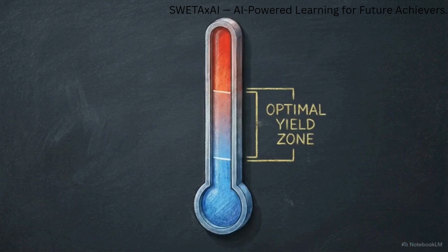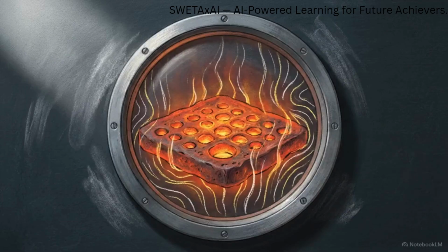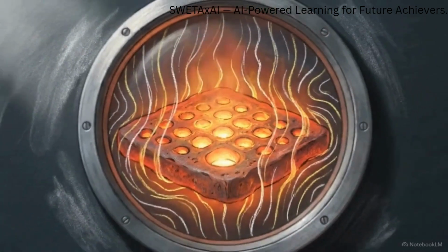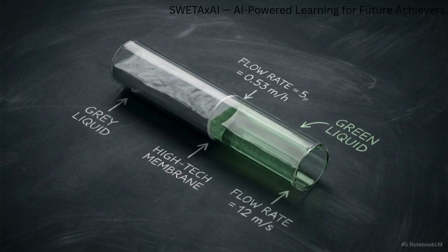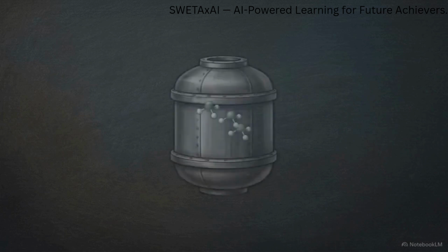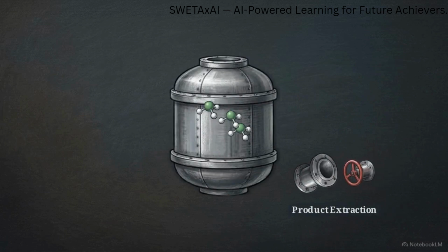The third and most crucial manipulation is a shift in concentration. A truly closed system is inherently flawed. If ammonia accumulates inside the tank, the reverse reaction will inevitably speed up and stall the entire process. Engineers solve this by building a continuous extraction mechanism. A condensation pipe actively siphons away liquid ammonia as soon as it forms. The closed system becomes an open loop. It extracts product from one end while simultaneously injecting fresh nitrogen and hydrogen into the other. This prevents the concentration from ever balancing out.